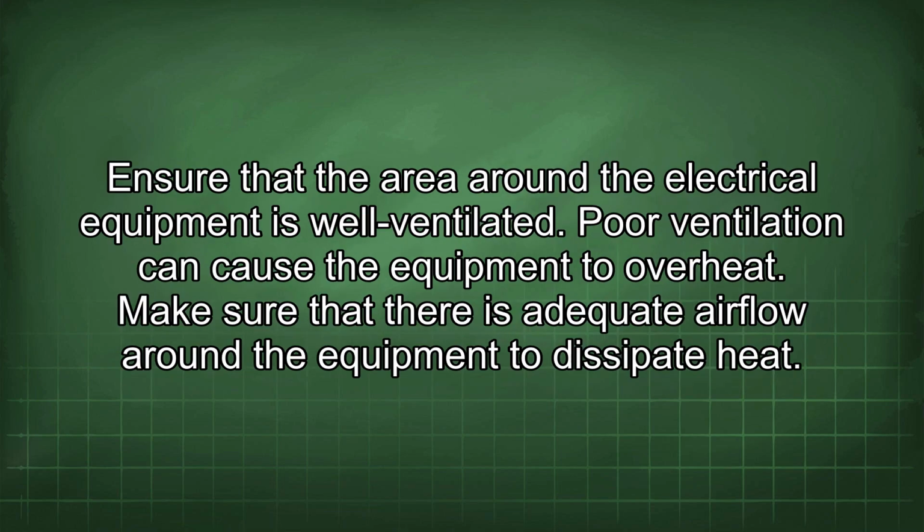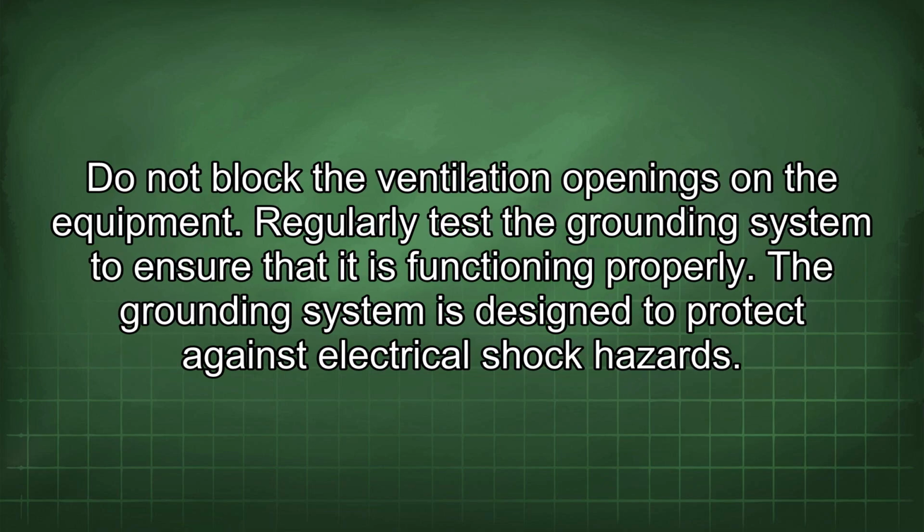Ensure that the area around the electrical equipment is well ventilated. Poor ventilation can cause the equipment to overheat. Make sure that there is adequate airflow around the equipment to dissipate heat. Do not block the ventilation openings in the equipment.